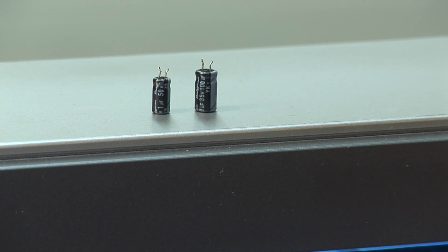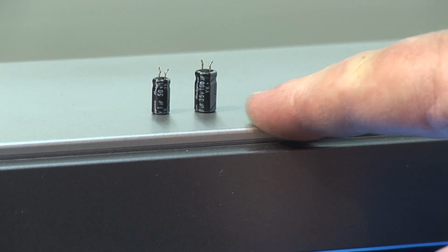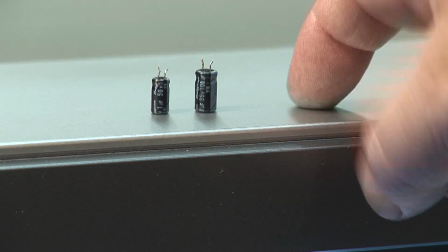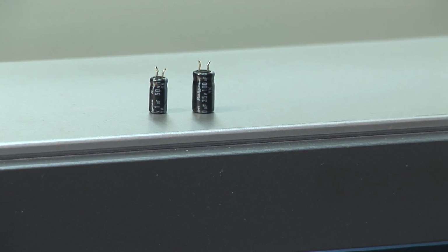But you can, in the case of the Toshiba with the red caps, you can use 105 degree and they will work just fine. But back in the 80s when there was no 105 degree other than the ones obtained from Toshiba, yeah, if you put a regular one in, you'd be changing it every couple months. But these ones here, I've put 105 in now. They'll be good for another 100,000 miles.